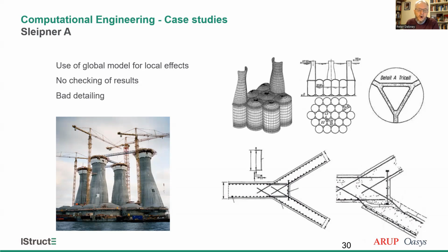So they manufacture on land, float it out, take it in a shipyard in Norway, take it out into the fjord, let in a little bit of water as ballast to keep things stable, and then tow it out into the North Sea and then sink it and fill it up and sink it to the bottom. And it was designed for an 85-meter depth of water, or 850 kilopascals, or kilonewtons per square meter if you prefer. Very high load.